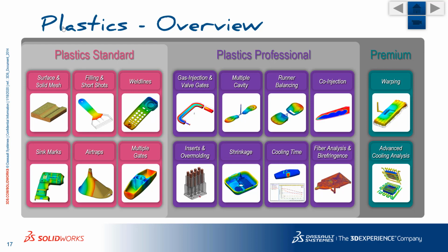Then plastics professional includes a lot of the mold maker type stuff. So multiple cavities, runner balancing, using inserts and overmolding. How much cooling time is needed to cool this part accurately, right? And then a couple of things like fiber analysis, understanding shrinkage, and then gas injection and valve gates, right? So a little bit more comprehensive, goes beyond just the filling stage, also includes what we call the holding or the packing stage of the process.